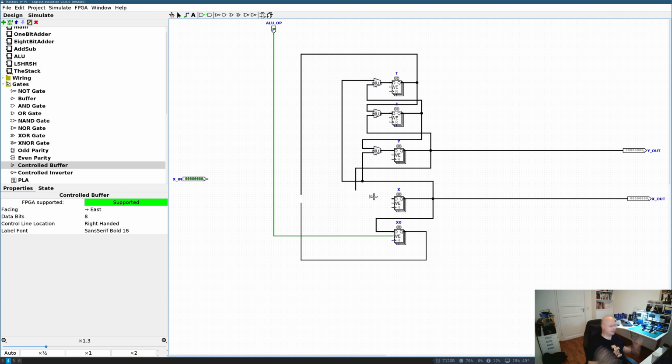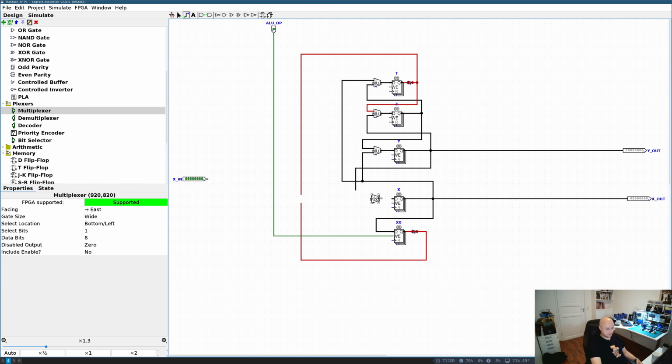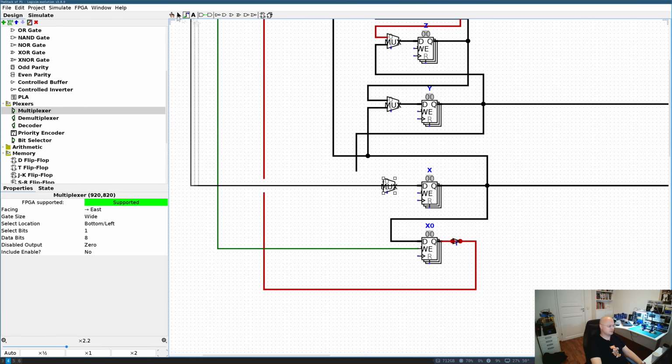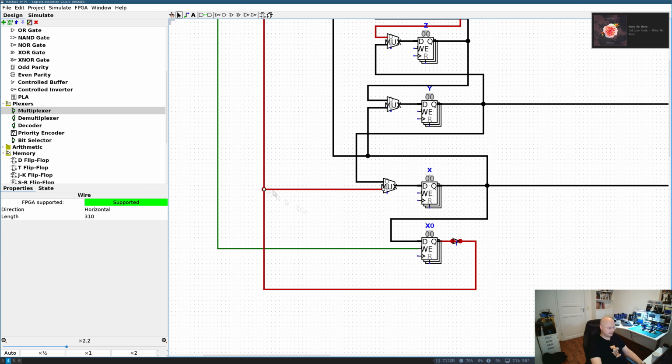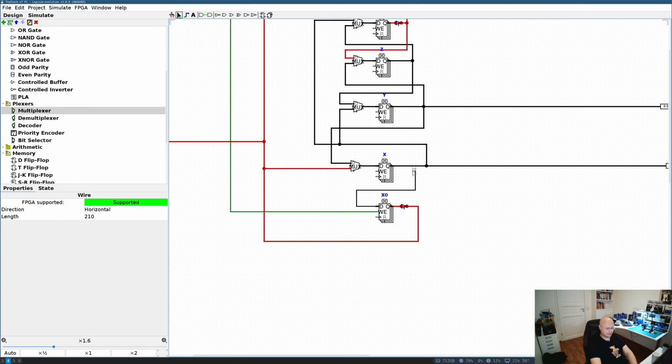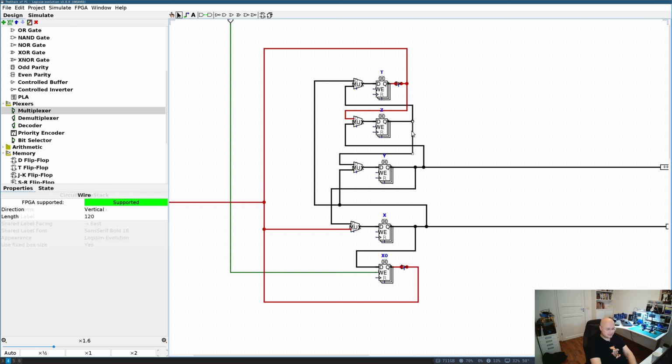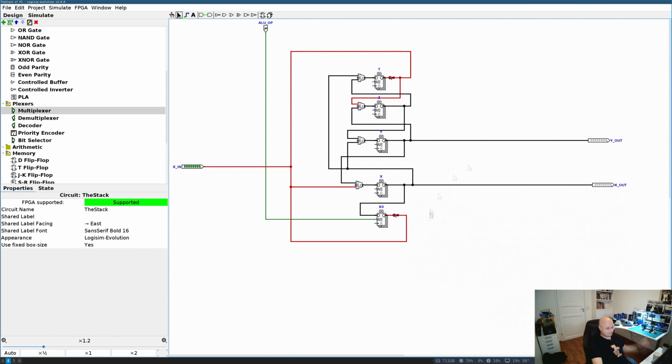to the same bus. With one small exception: as Y is always connected to the Y out, I cannot use the output enable pin of the Y register. Y should be connected all the time, and because of that I will have a multiplexer that will choose the input for X between the Y register and the X in bus. Another option would be to put a tree of multiplexers, but I don't want to go that way because of propagation delay. We'll discuss propagation delay another time.